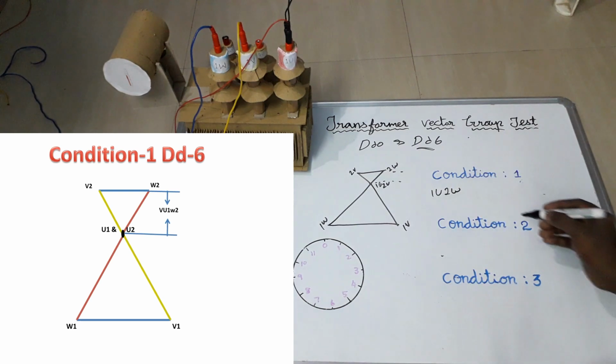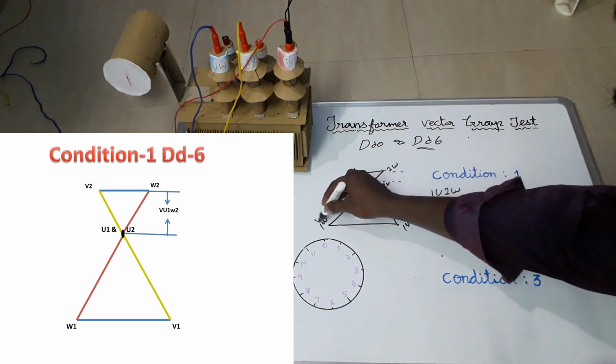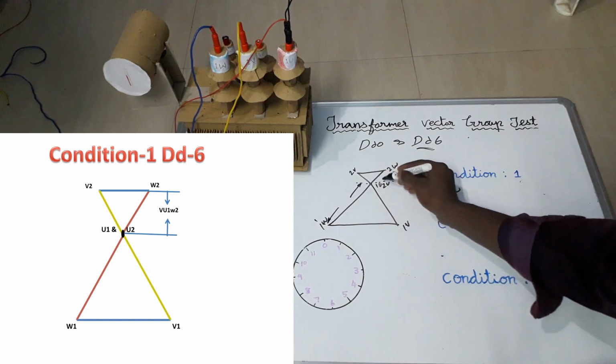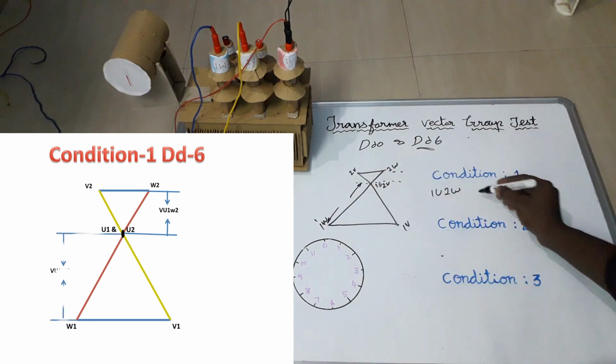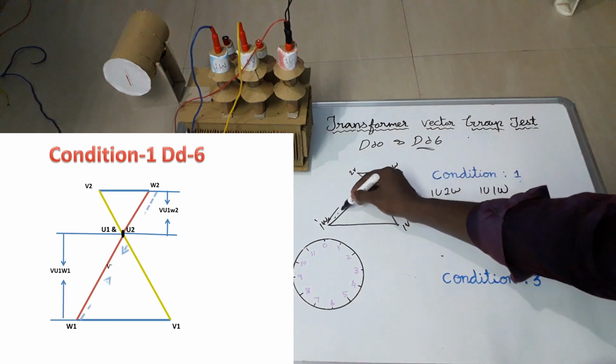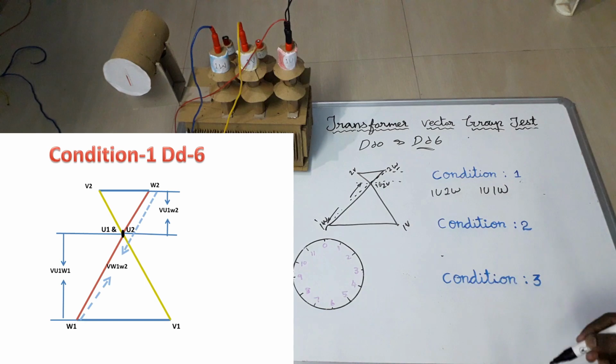Second, I am going to check voltage between 1U and 1W. Third, I am going to check voltage from 2W and 1W.